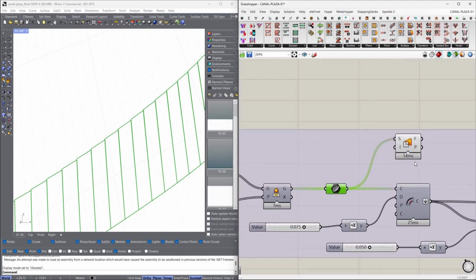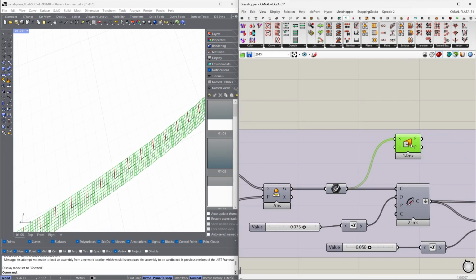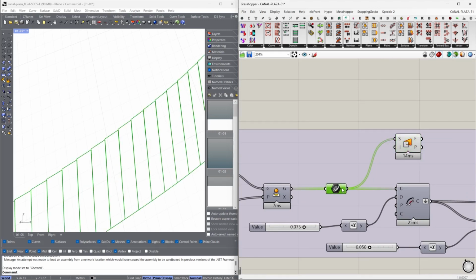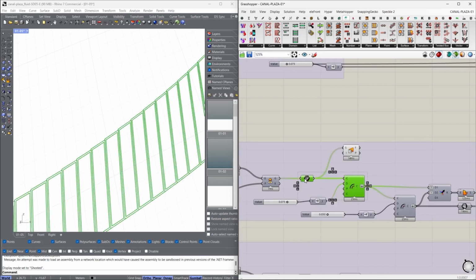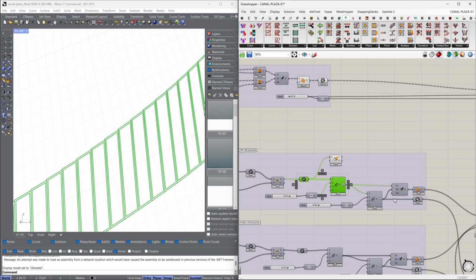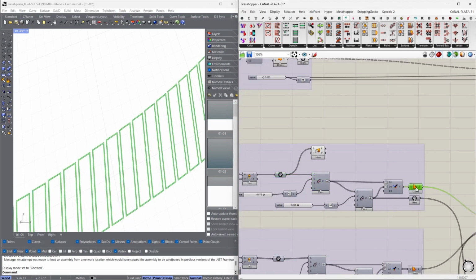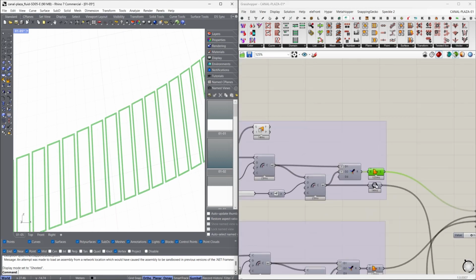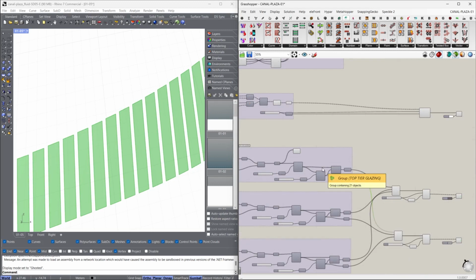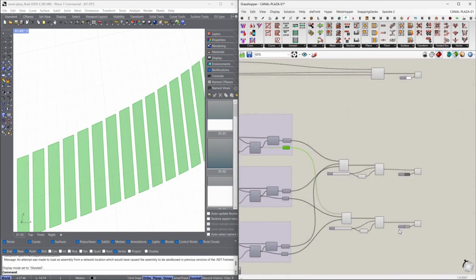And then I just did a test here, planarity or planar test, and if I just hover over here, we've got 260 values, 260 polyline curves, and it tells me here that all 260 of them are planar, so it was successful. And because these curves are planar, it's easy just to offset. So we've got the original one, we've got the offset, and then from these offset ones we can generate the frames on the edges, and we can also generate the glass planes. And then from there it's quite a simple exercise.